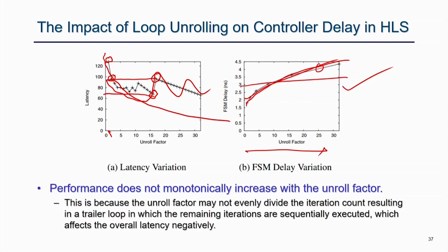So, your design is not meeting the timing. If you just unroll by say 20, you are violating the target clock period, so this is a serious violation. So, there should be some trade off. You can see here probably this is the best choice. In this case your latency is minimum, which is 16, but in this case the total delay is say 3.5 or something, and suppose your target clock is 3, you are not meeting the timing. So, this is the trade off